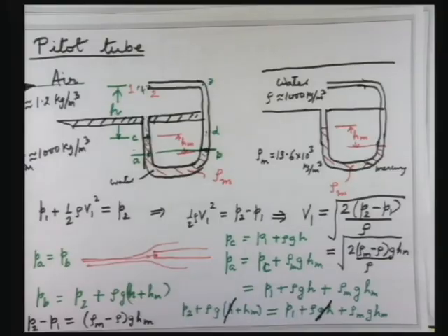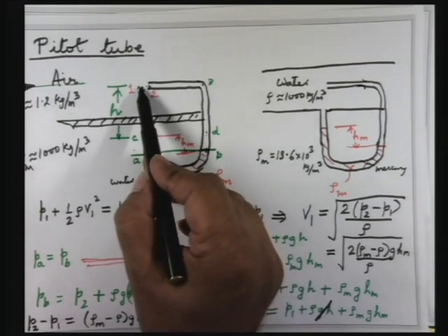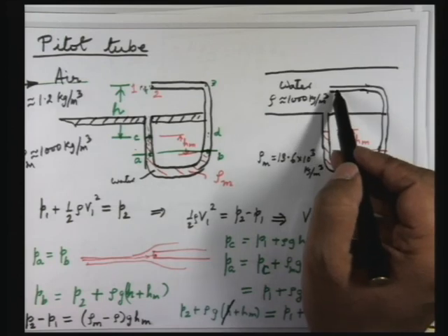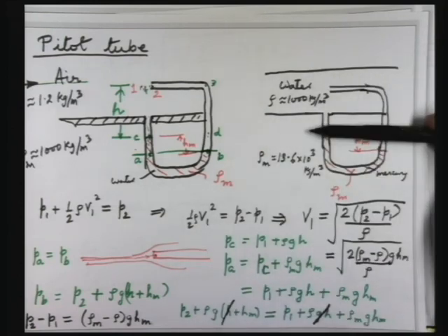Hello. Hello, sir. In the case of a manometer, once we are connecting with the pipe, we should specify that the pressure measured at point 1 should have zero velocity, along the center line. No, the point 1 is not zero velocity. Yes, sir. So it should be the velocity of the fluid particles which adhere to the wall. Not, I think, the center line. No, I am not talking about the center line here. This could be anywhere, you could have it in the left limb.